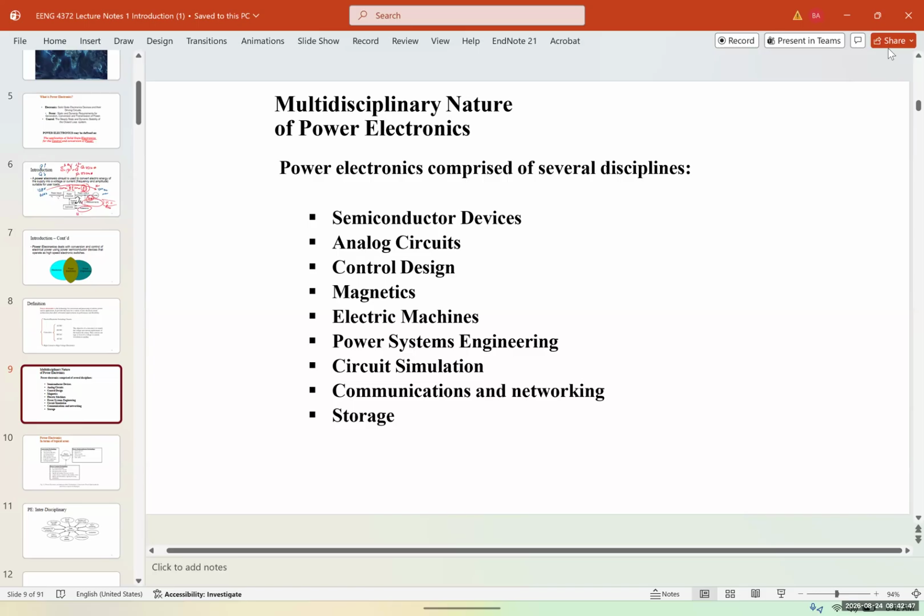It's a combination between AC and DC motor, and without power electronics, without having the switching and PWM system, you cannot convert a DC battery to be able to run a BLDC motor. So we won't have drones. A lot of these high efficiency EVs also use BLDC motors.